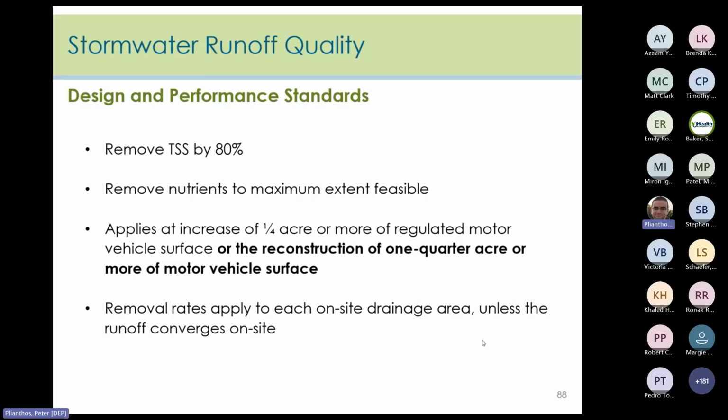It's the things that make the water look turbid or cloudy. Stormwater management measures shall be designed to reduce the post-construction load of TSS in stormwater runoff generated from the water quality design storm from all new and reconstructed motor vehicle surface.